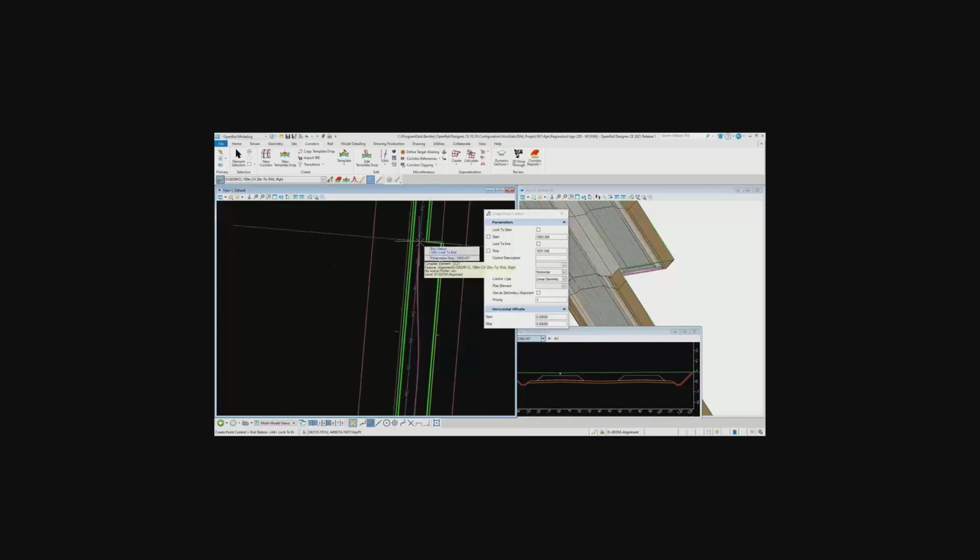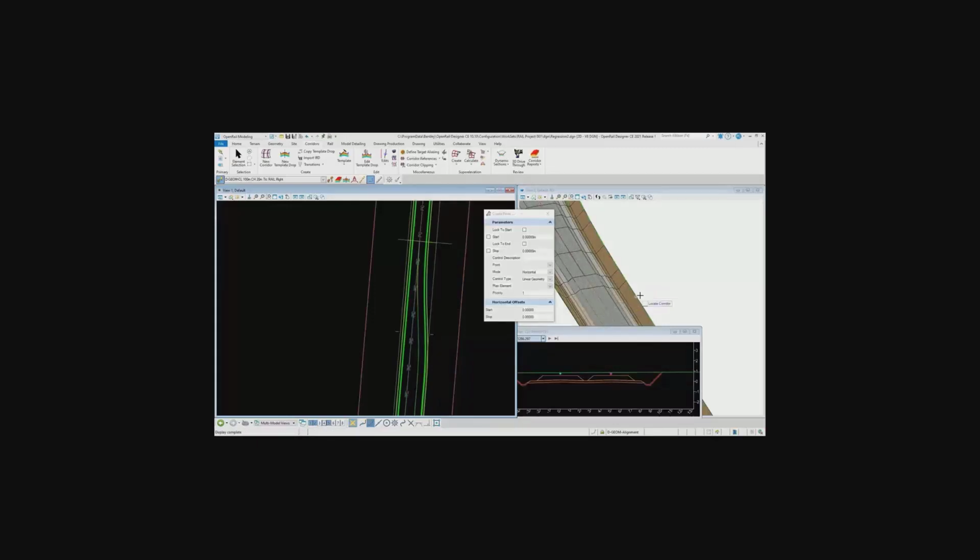So in this case, using the same point control tool, you are going to manipulate the point in the second template, which is actually the CL2 point, and then follow or adjust according to the turnout geometry. Okay, you see here?